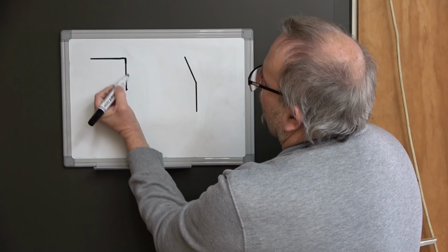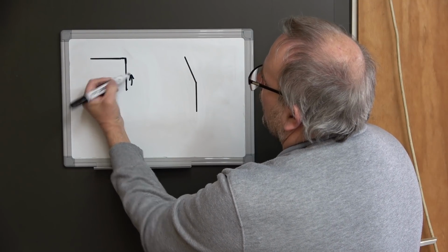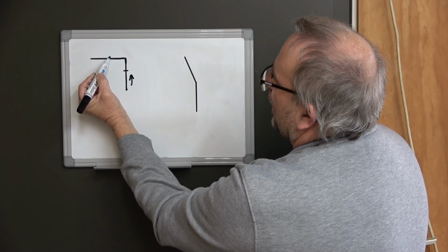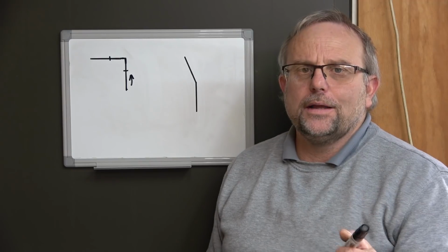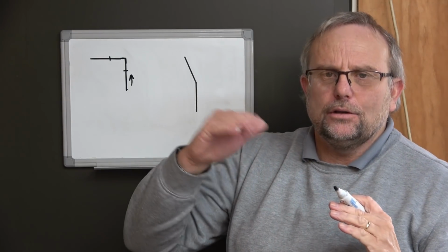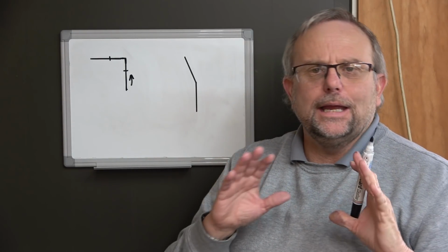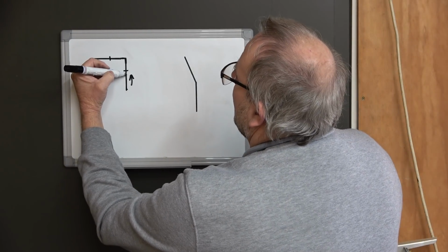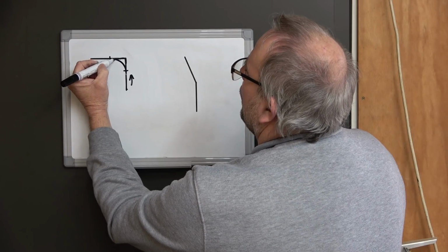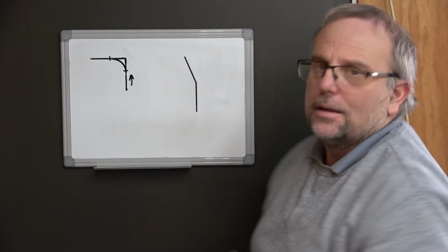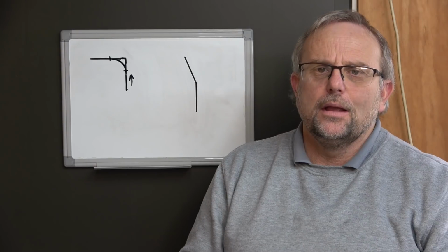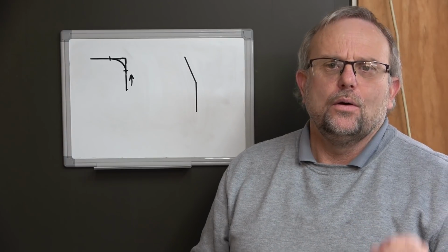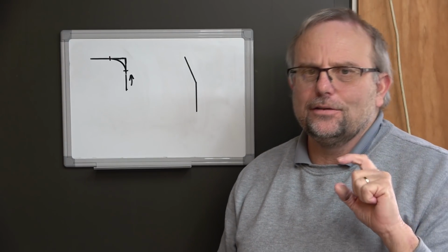So 15, if I'm traveling in this direction here, 15 millimeters from the end of my line there and there, I can start making curves so that I can keep my constant velocity. So I can come up here, and then I can start turning like this, and then keep moving. So I can only make those changes to the toolpath when I'm within the designated distance at the end of my line.